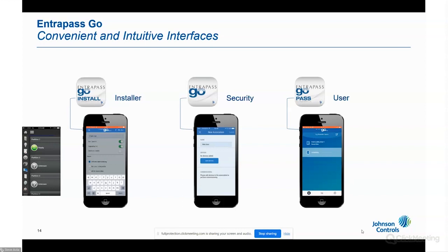This is the KT1 controller. It has a built-in PoE and PoE Plus, as well as a 12-volt input. Encrypted IO Smart reader communication, secure communication with 128 AES encryption, 4 built-in inputs and 2 built-in relays.